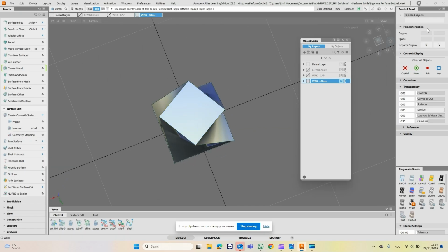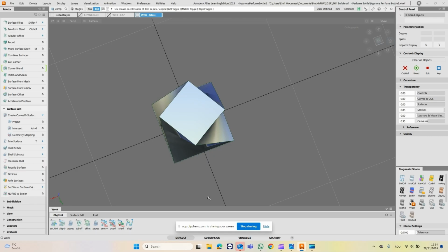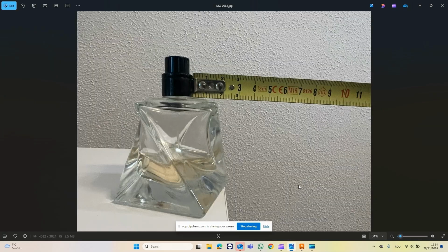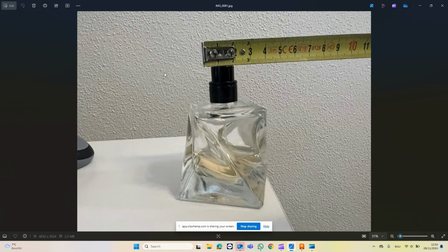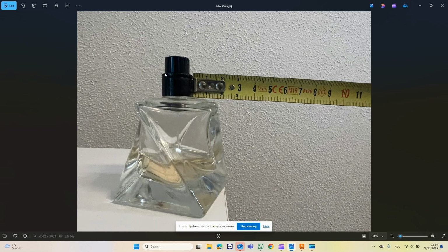how do we build this centerpiece here? Now what I want to do is I want to make my work as easy as I can. So that bit at the top there, I will be building a rotational object, so a revolve, and that's a new tool for you, the revolve tool. If that's 2 centimeters in diameter, and this is give or take 2 millimeters, 2.5, that's already enough info for me.